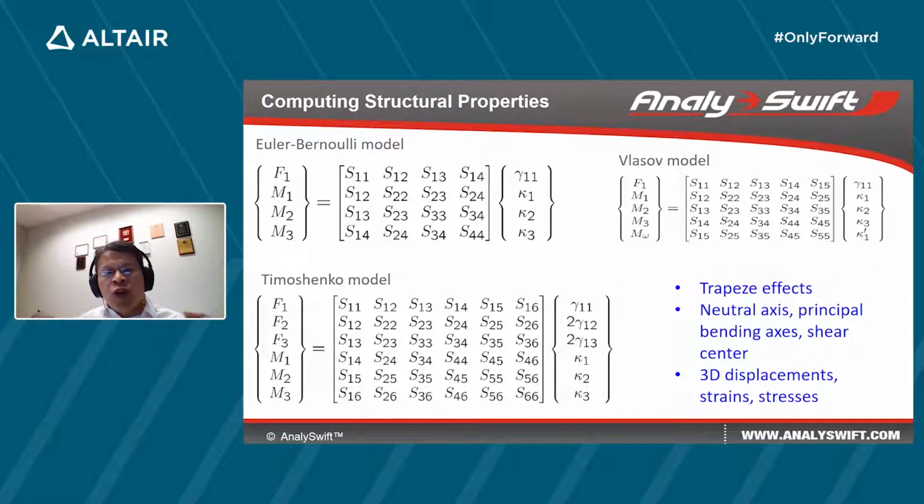When the beam is made of an open thin-walled section, we find out that the one variable for the torsion is not sufficient because that only describes the uniform torsion. We also need to account for the restrained warping effects due to the open thin-walled section. So we introduce twist rate, and that will establish the Vlasov model. Because of the complexity of the geometry and also the anisotropy of composite materials, the stiffness matrix could be fully populated, which means that the corresponding beam analysis should also take the fully populated stiffness matrix.